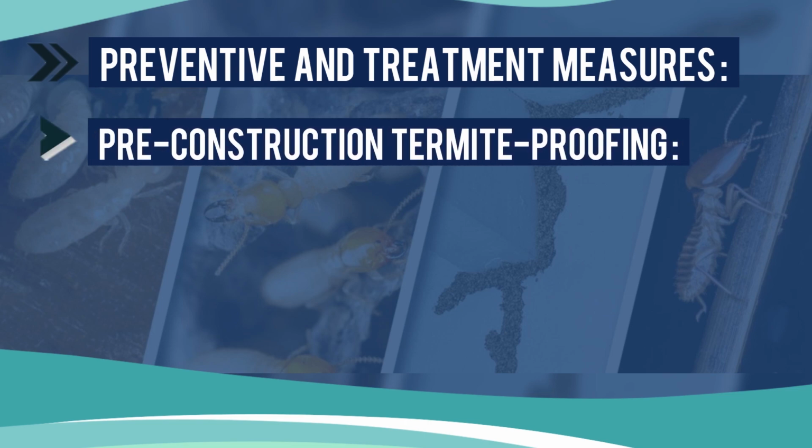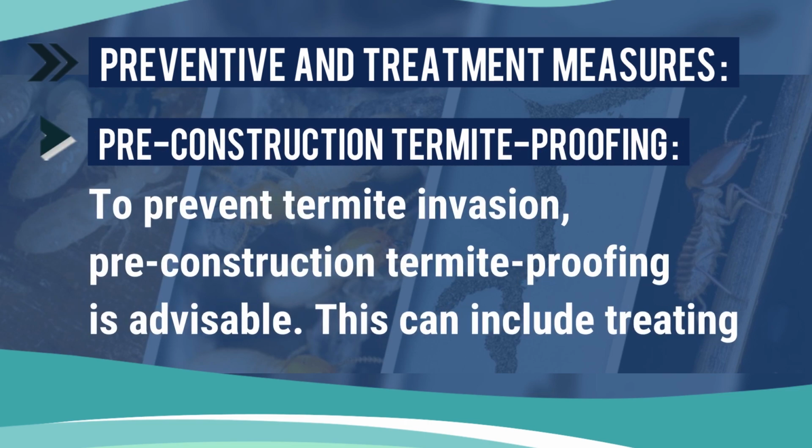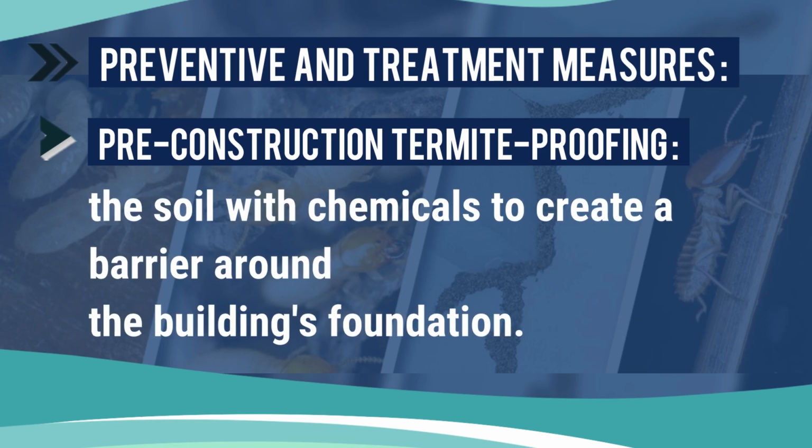Pre-construction termite proofing. To prevent termite invasion, pre-construction termite proofing is advisable. This can include treating the soil with chemicals to create a barrier around the building's foundation. Then the post-construction termite proofing.